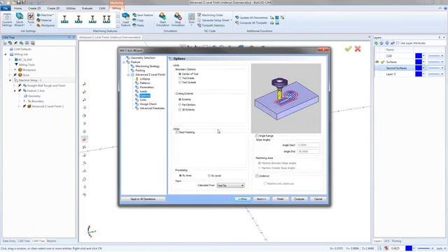All right, now when we get to the options with this toolpath, the part that's needing to be cut is the undercuts, and that's the only thing that actually needs to be cut. If you come in over here and you just click undercut, it's going to use this lollipop to try and cut the whole part, but you're also saying, you know what, as you're cutting the part, go ahead and do the undercuts at the same time.